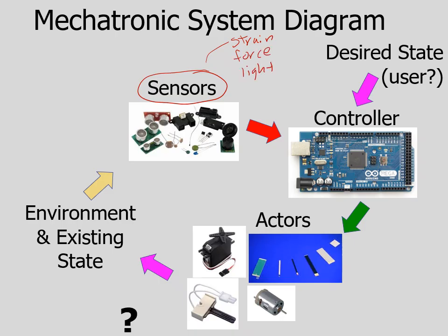We're going to do that in our final project. Some range sensors, we will see that. Those can be analog devices. Other things we could talk about, there's many others. Sound, could be motor speed, many different things can be measured as analog signals. And if we want to be able to take them in, store them, transmit them with a microcontroller, we need to be able to convert them to digital.